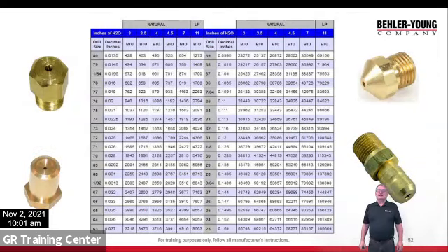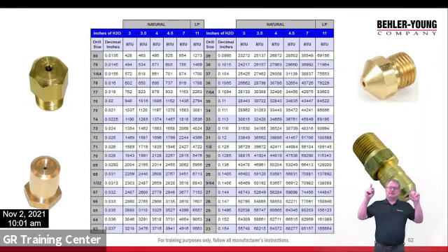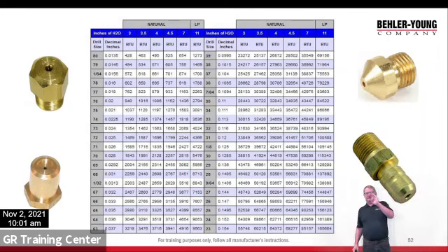Okay, this little chart here. So now we talked about gas pressure. Now, hopefully you guys can see this clear enough. It's a little fuzzy on this, but I think we can make it out. But anyways, all these little brass doohickeys here are called orifices, right? They have a specific size hole in them, all right, for metering the specific amount of gas, propane or natural, to the burner. All right, so we already talked about the pressure, because the first thing in how much gas we deliver is what our pressure is going to be.